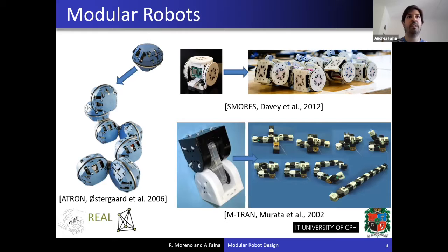And importantly, they also have attaching points between them. You can have different connectors, and then you can attach these modules together to make a bigger robot, because usually one module alone cannot do much. Basically, most of them cannot even move. They can just move their own actuator, but they cannot locomote on a terrain. So in order to make robots which are able to work in an environment, you need to attach these modules together and make a configuration of modules.